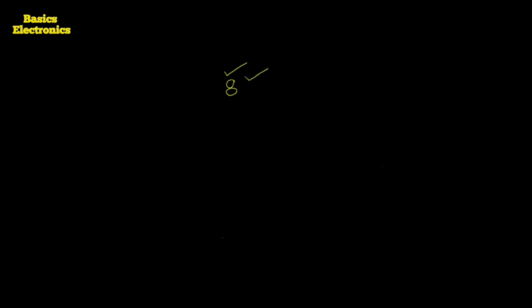One more input is the common input. That input we call the strobe input or the enable input. This strobe input or enable input is the input which makes the whole demultiplexer be in enable condition, or the whole demultiplexer be in the disable condition.